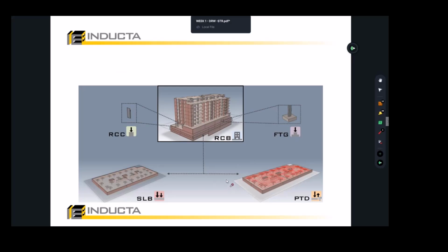Now, this software is one of the available packages inside the suite, and the suite has different packages. They have a package that engineers use to design slabs, like floors, whether beam slabs or flat slabs, etc. They have other packages which design post-tensioning slabs, where they have cables.